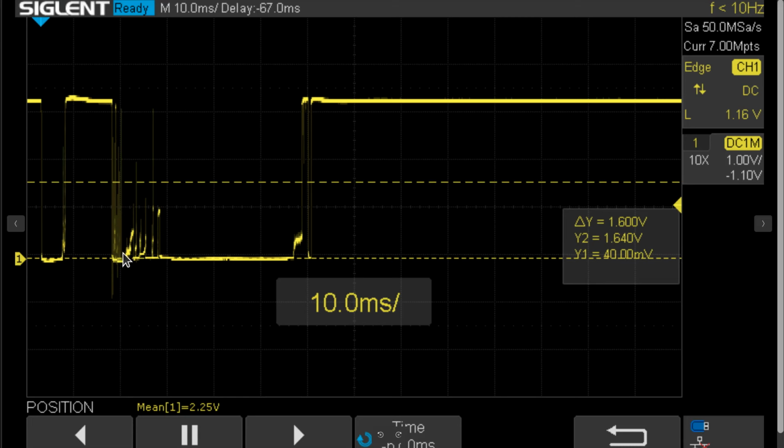Oh, it changed again. Okay, it's going to start counting every time it thinks the new signal is not what it is currently reporting as its output. So if its output is currently 1, which is the case here, right? Maybe I should open with that. The input and the output are both 1 here. The input changes to a 0. The output will stay a 1 until the counter expires. If it whipsaws back up here, it'll go, oh, that was just a false alarm. It resets itself and it stays 1, no harm, no foul.